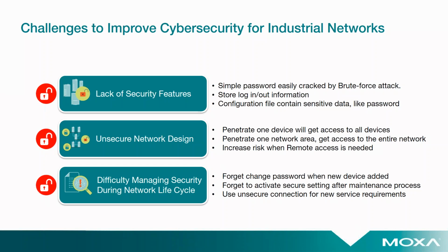The other one is unsecure network design. Penetrate one device, get access to all devices. Penetrate one network area, get access to the entire network, right? We don't want that, because now you're also having things like somebody remoting in to access a device to do some maintenance, and you want to make sure that you limit and monitor exactly what that person is doing. You might want to have the security in place to protect your serial or your legacy devices